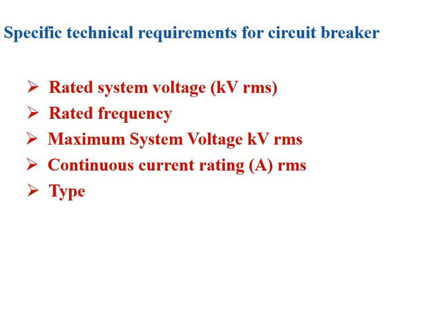If it is required to be installed in, say, a package substation which is enclosed, that is called an indoor substation. So indoor and outdoor depending on the location, and depending on the insulation, air circuit breaker, SF6 circuit breaker. Air circuit breaker can again be subdivided as air blast circuit breaker or air break circuit breaker, etc. So depending on various categories, various types of circuit breakers are there.